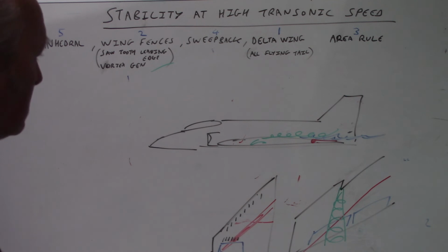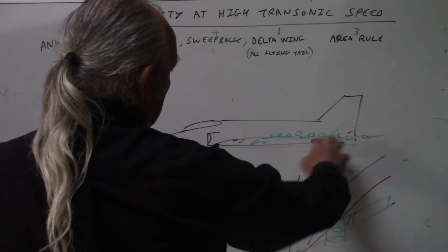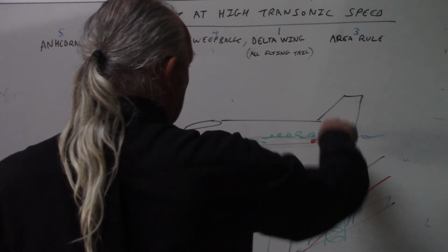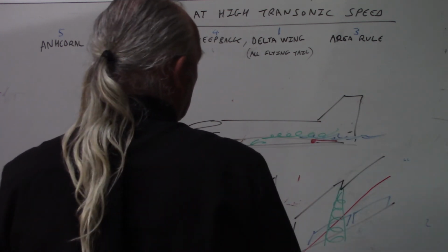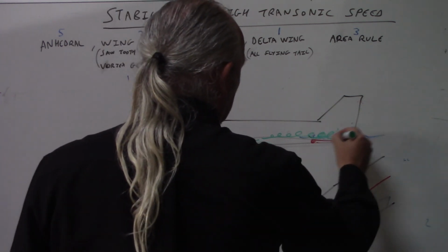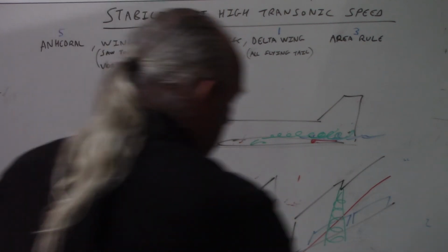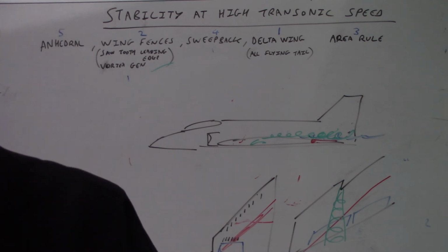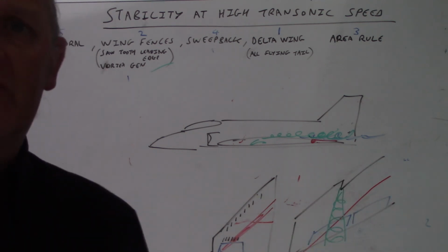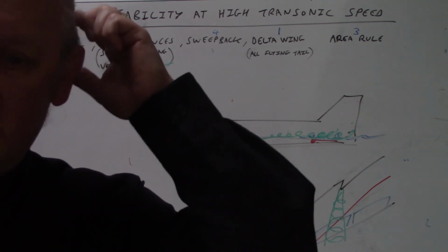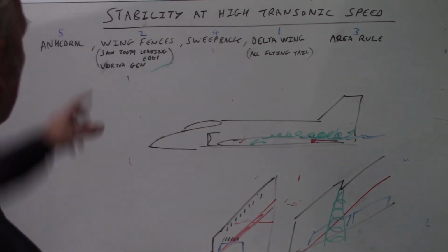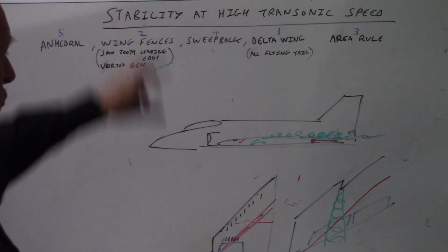And what they do is, where your control surface will be subjected to separated flow, they create a vortex, right? And that vortex flow over the control surface is better than turbulent flow. It's not as good as laminar flow. There's always drawbacks in engineering. If you can't have laminar flow, you might as well have vortex flow. Right. So we've done sawtooth leading edges, vortex generators, wing fences.